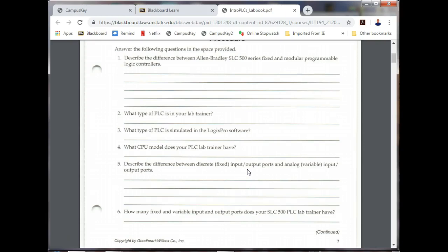By the way, on these, if you're on the station assigned to this PLC, this is not the number of inputs and these are not the number of outputs. The number of inputs and outputs your PLC has, you have to look at the PLC. This is just a mount that we mount the PLC on and then we wire it up, right? Understand? That makes sense? We had the problem last semester where people got on this and said it had 16 inputs and 16 outputs.